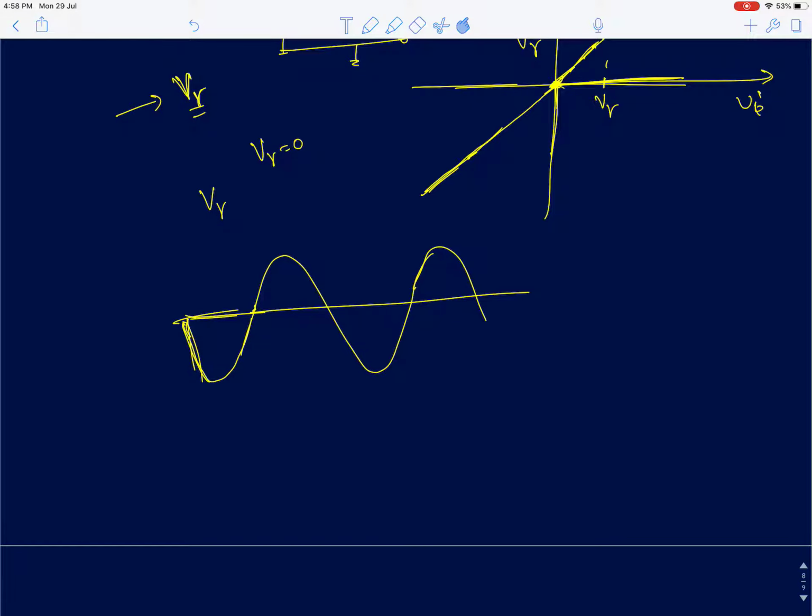You are actually going to get, I'll draw it in a different color, the same output when the output voltage is negative. But in the positive half cycle, when your output voltage reaches V gamma, it will flatten out like this. Such a circuit is called a clipper. So your output will look something like this.